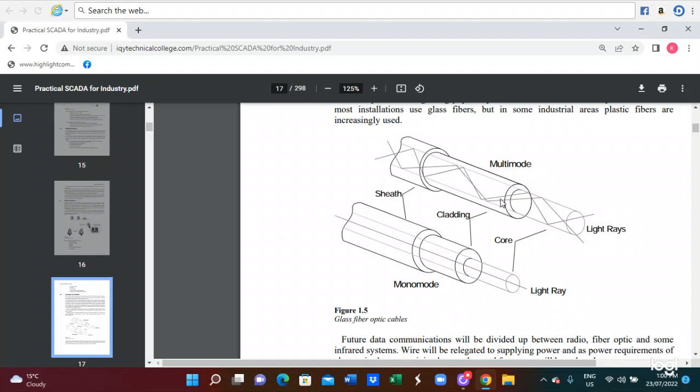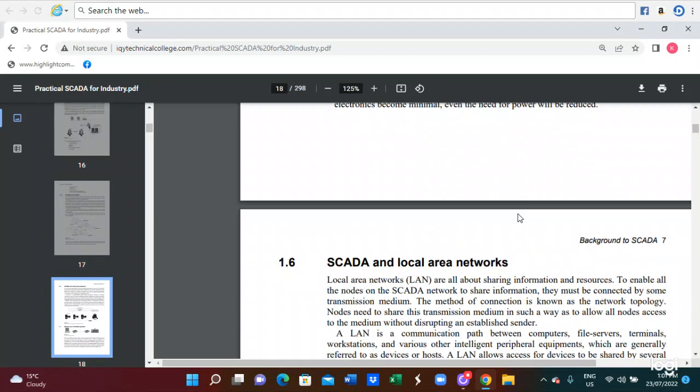We use a multi-core cable or a single core cable. These cables are utilized so that their installations prevent absorbing any interference. Any interference signal needs to be eliminated by the protection layer. So this is the data control cable. Those data control cables are utilized in the programmable logic controller and the SCADA system wiring.